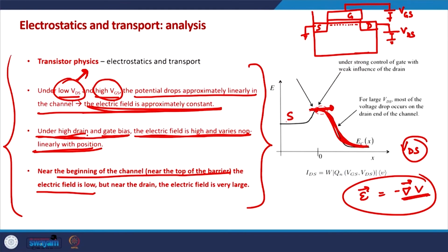We have also derived, very qualitatively I would say, a glimpse of how the IV characteristics of the MOSFET look, in which we considered that the current going from the source to the drain side is ILR, left to right, and the current from drain to source side is IRL, and by relating the current to the barrier height, we have also seen how this current is dependent on the charge in the channel and the velocity of the electrons with which they cross the barrier.